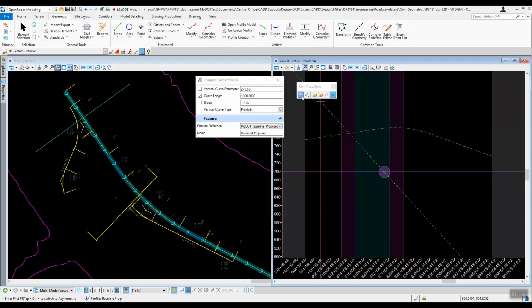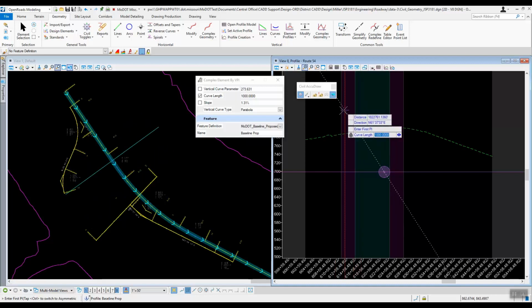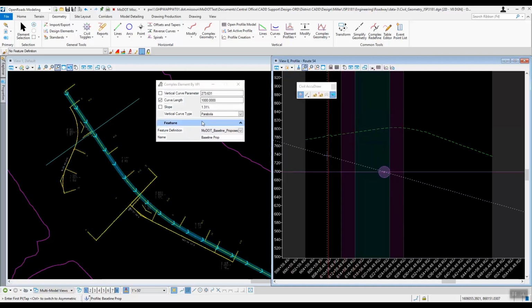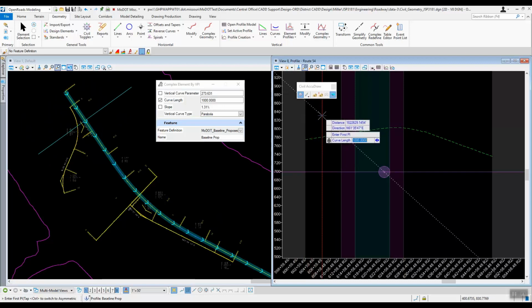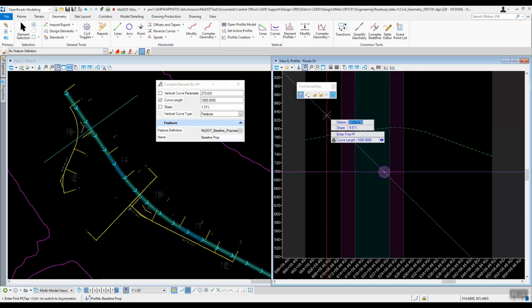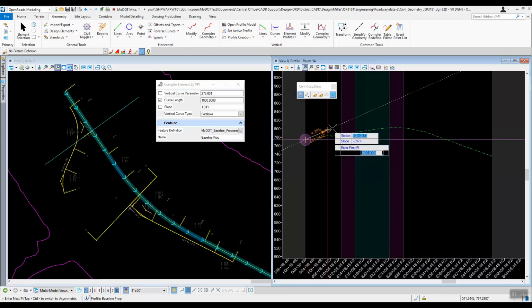With Civil Accudraw going out here on the screen, I'm going to make sure it's active. Since my dialog was over here in this window whenever I was filling this information in, when I move into my profile window, distance and direction are what it says it needs. So what we need to do is pick that slope option, and then that should change it to station and slope. Okay, we're starting here at the beginning of existing ground, so we will left click at that snap location.